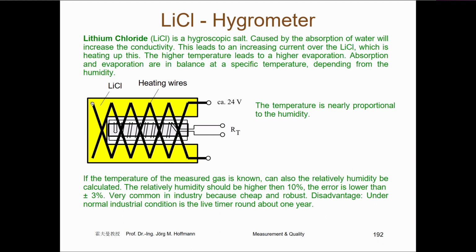These two wires are not connected. You see, they are separate in this material. And when you have now the airstream around the sensor, the salt takes the water from the air, and you get from one wire to the other wire a current.